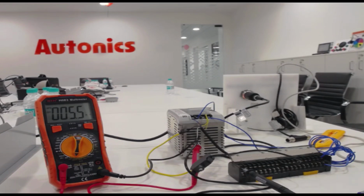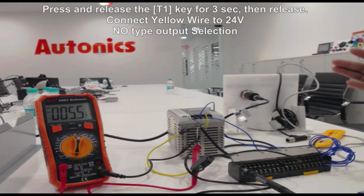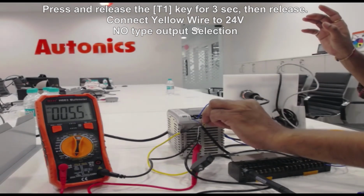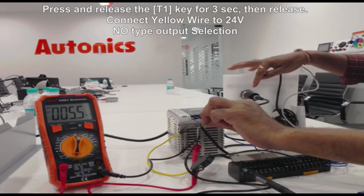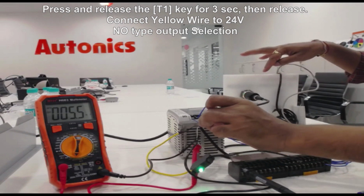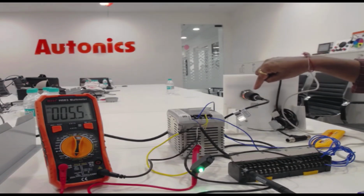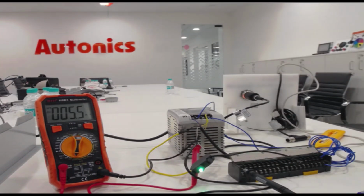Now we need to teach the normally open type output. So we need to connect the yellow color wire to VCC for 3 seconds. 1, 2, 3. Yes, we can see the sensor also came out of this teaching loop, and the LEDs are stable now.